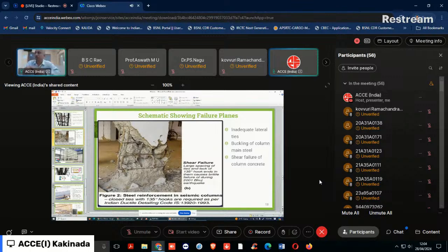On the side towards the seismic loading direction, the columns will be subjected to a much lesser load. It can even be a tension. On the opposite side of the seismic acting forces, the column will be subjected to gravity loads plus, in addition, higher axial forces due to the seismic loading. That is, it is subjected to higher compressive loads when compared to the gravity loading.